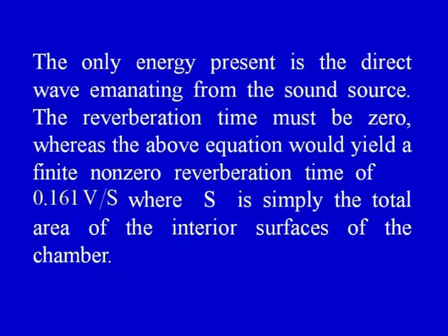The only energy present is the direct wave emanating from the sound source. The reverberation time must be 0, whereas the above equation would yield a finite non-zero reverberation time of 0.161 V by S, where S is simply the total area of the interior surfaces of the chamber.